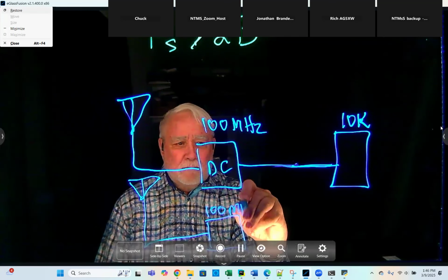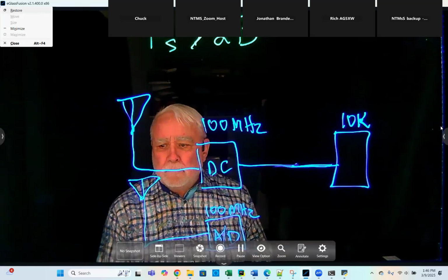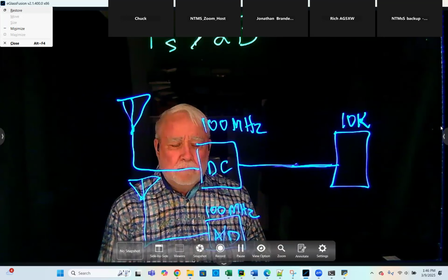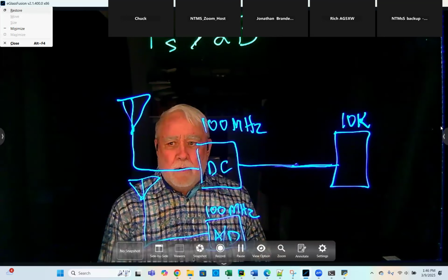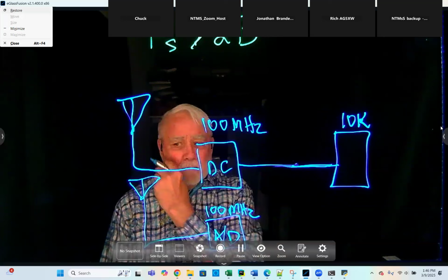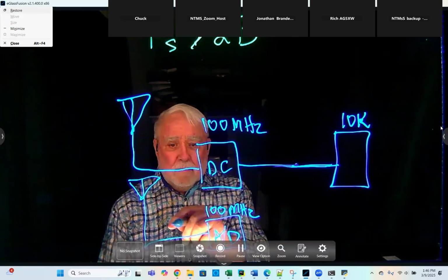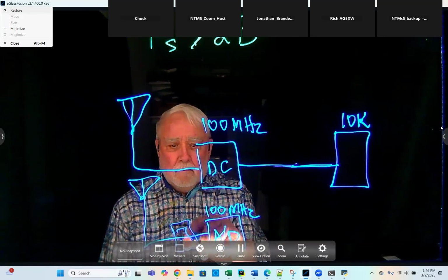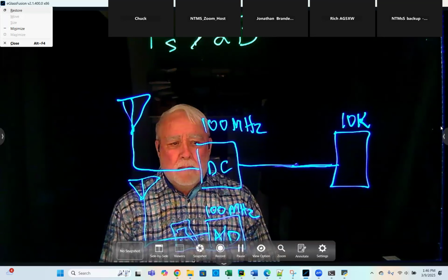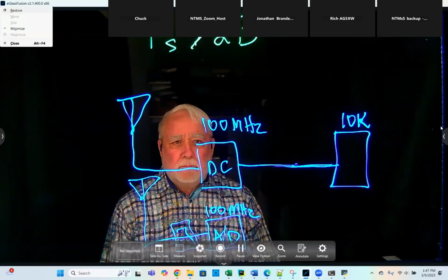Well, the Flex Radio does that today. They've got a 243 megahertz sampling, so it could go up to 100 something megahertz. Is it tied to the antenna, basically? Oh, no, actually they have filtering to limit it, but their converter could do that. And I would go so far as to say you can get into the higher Nyquist zones, and that does work.